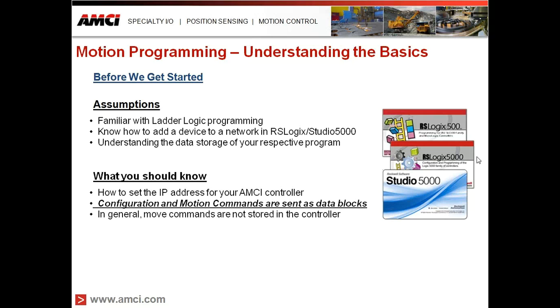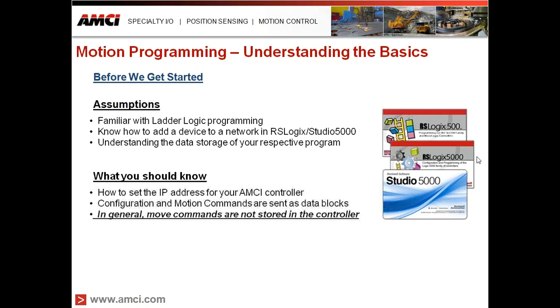You should also know that configuration and motion commands are sent as data blocks. And that's really what we're talking about today, those data blocks and how they're manipulated within the programming environment. And you should also know that in general, move commands are not stored in the controller. Really what we're talking about here is once I've executed a move, the device needs to receive another command for the next move. We're typically not going to store a series of commands and then just trigger them through an input. That's not how these devices work. They're designed to communicate directly with the PLC and receive commands from the PLC directly.